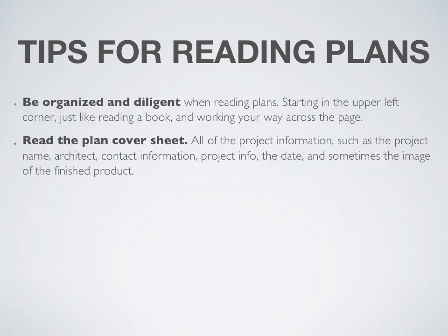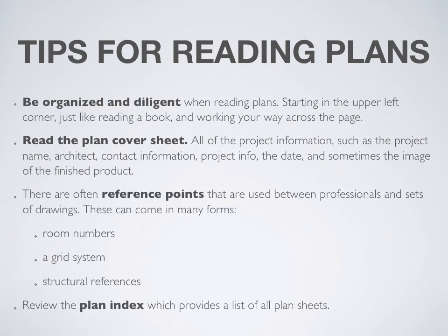Some other tips are to be organized and diligent while reading plans. You want to start like in the upper left-hand corner, just like reading a book, and kind of work your way across the page. Read the plan cover sheet. It contains a lot of project information such as the name of the project, the architect, contact information, project info, date, and sometimes an image of the final product.